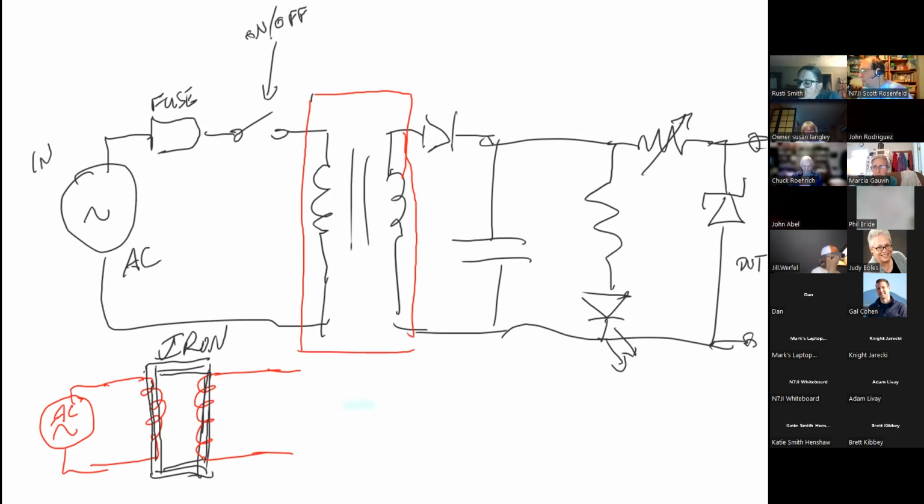When would you ever use a step-up transformer? On the other end. Let's say you're at the power station and you're generating voltage at 3,000 volts. And your high voltage transmission lines, which are what you, for instance, drive under when you're on the interstate, those are operating at 345,000 volts, maybe 600,000 volts AC. Some of them are operating at 800,000 volts AC. Some of them are operating at millions of volts DC, but we're not going to go into that because that's a much more complicated circuit.